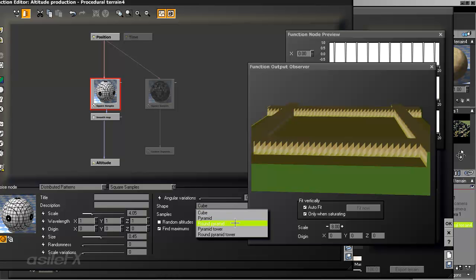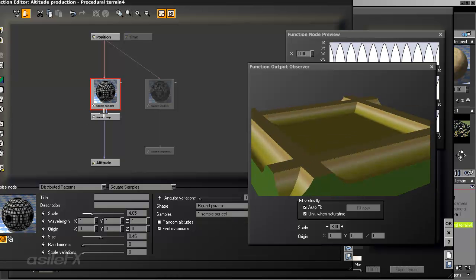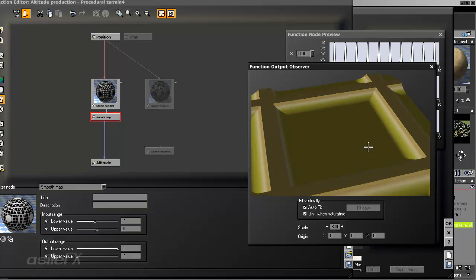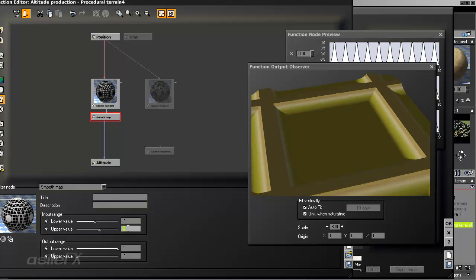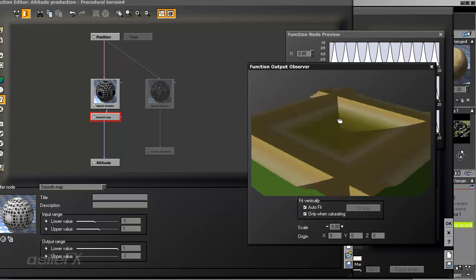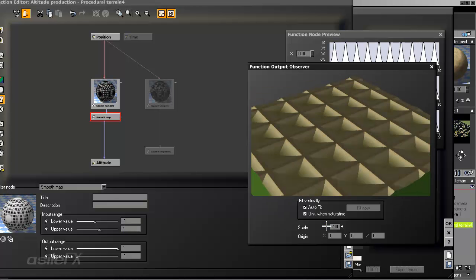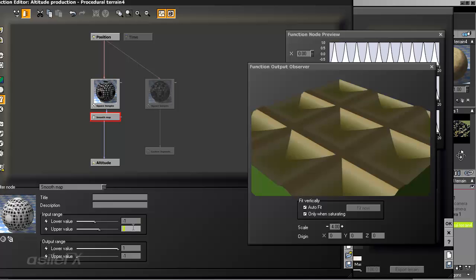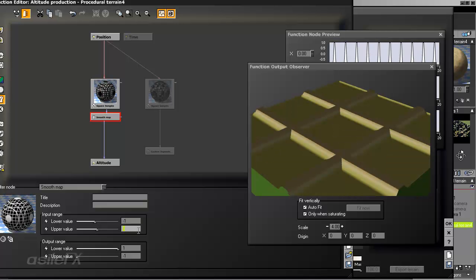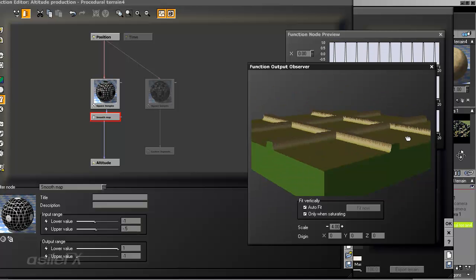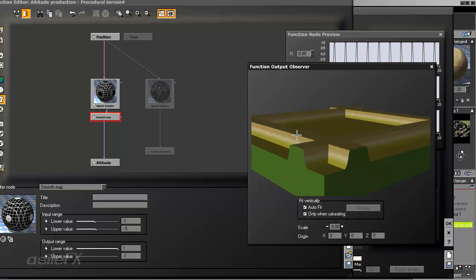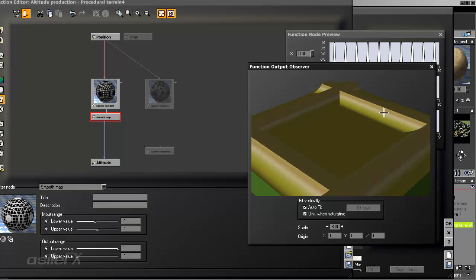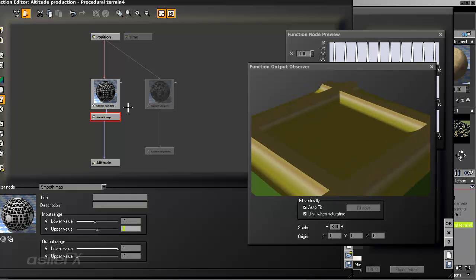So instead, what we have to do is use something rounded, and then I'm using the smooth map to clip off some of the top parts, because otherwise it's going to go down really deep into that pyramid shape, which, if you're looking for that, then that's the way you achieve it. But otherwise, what you can do is clip it out. We could bring it in further if we wanted to, negative 0.5. Eventually, it will reach a point where it will become too harsh of an angle and start to tear again. So you just got to be careful of that when you're using this technique.